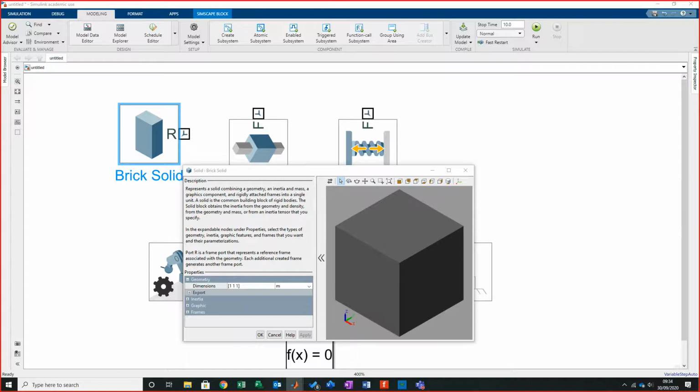What I'm going to do is probably half of all that. So these are dimensions. These are your typical dimensions in any CAD, any sim systems, any binary methods, anything like that. So this is simply X, Y, and Z. So what I'm going to do is go 50, 50, and 50. I'm not going meters. I'm going to drop my meters and go to millimeters. I'm going to press F5 to update. Now this is a bit more like what I'm actually after.